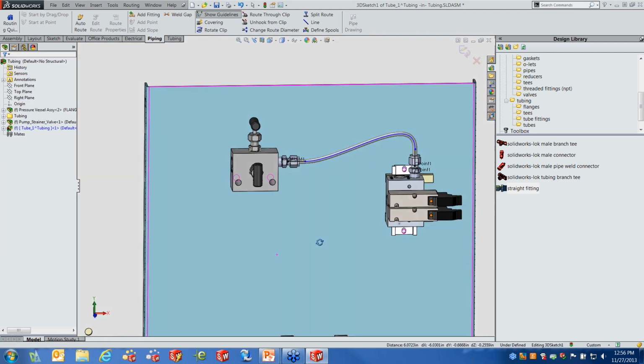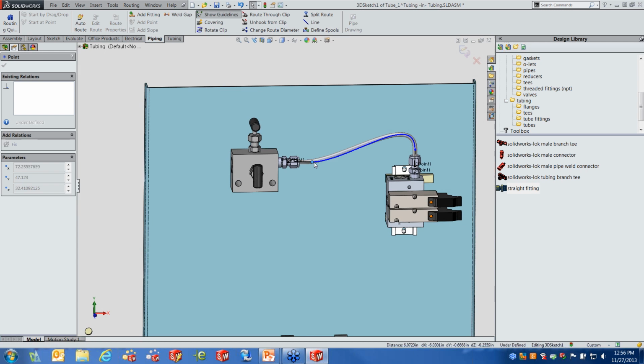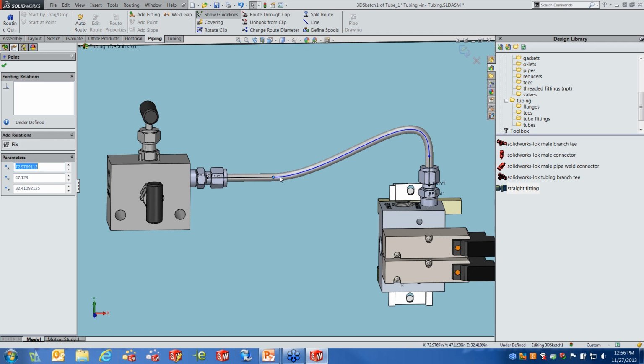Now, this acts a little bit different. I still have the ability to adjust, but this is a spline that I can control. It has some added capabilities. Watch as I drag this length a little too short. When I've exceeded the bend radius of that piece of tube, which is all stored in the configuration and design tables, it now alerts me that that has happened as well.